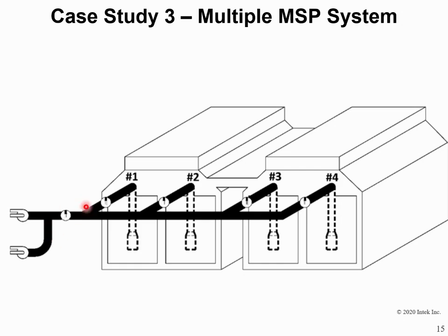One probe is installed in the common, and the other two probes are allowed to be moved between the four other vent line locations. For this leak audit, a fourth probe was installed and the common probe was moved so that each vent line 1 through 4 could be monitored.